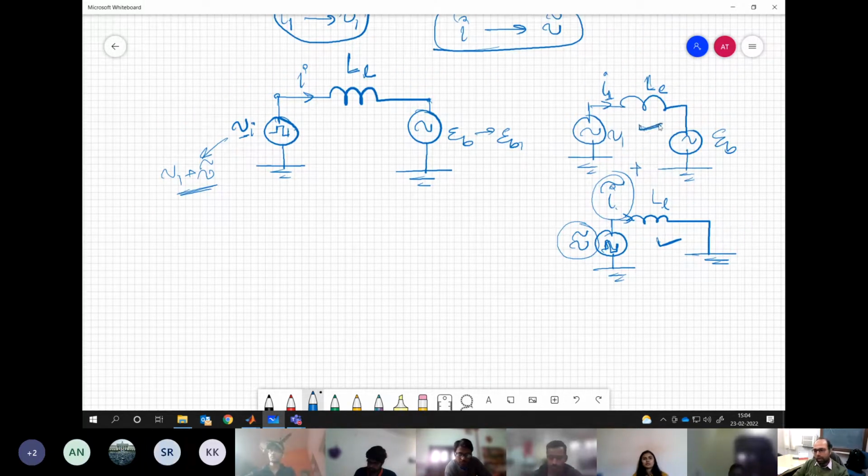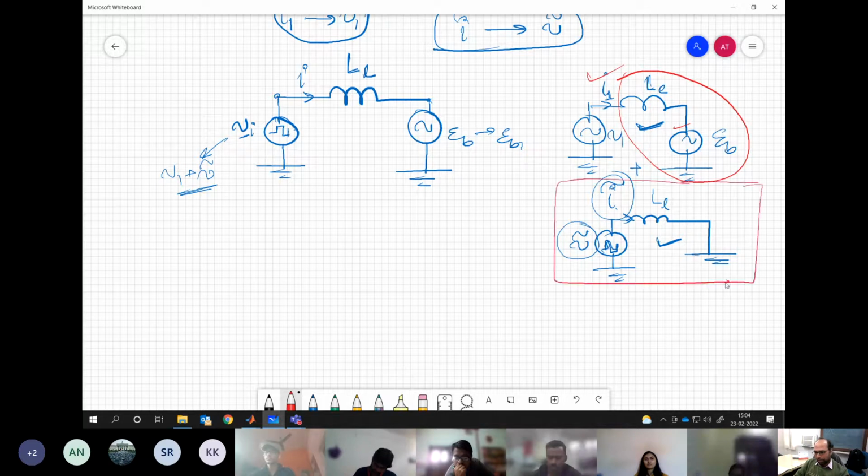Now this decomposition is for an individual machine. Let's say you have PMSM, so you will have back EMF and then leakage, and you solve this system. If you have an induction motor, you have the per phase equivalent circuit connected across the voltage. You solve that, get the fundamental. However, this part, what we are doing for the ripple, is kind of common for everyone. Common in the sense only the value of leakage and what you are feeding will change. That's all. The method will remain the same.